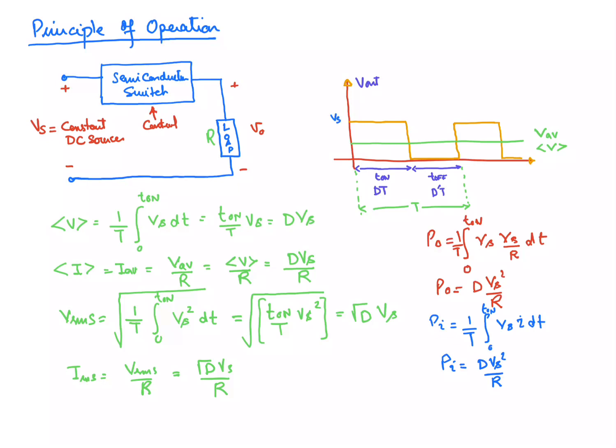Okay, now when your switch is in the on state, then the power is delivered to your load, and when it is turned off, no power is delivered to the load, but the average power that is delivered can be calculated by this one. So now this resistance appears on average different at the supply terminals, because if you consider a cycle, for this time you are delivering the power, and over here you are not delivering the power. But now if I say what is the average resistance that will be appearing across the supply terminals in a cycle, what will that be equal to, because the resistance is turned on and then it is turned off. So how do you define the average resistance?